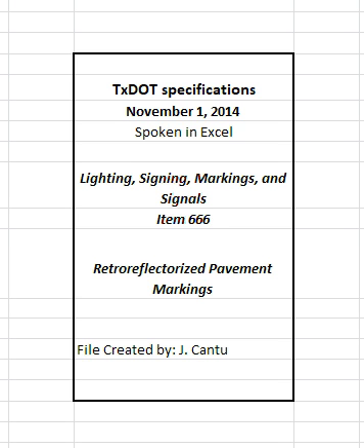Take a minimum of 10 more measurements after 10 days of this second application within that mile segment for that series of markings. Restripe again at the contractor's expense with a minimum of 0.060 inches, 60 mils, of Type 1 marking material if the average of these measurements falls below the minimum retroreflectivity requirements. If the markings do not meet minimum retroreflectivity after this third application, the engineer may require removal of all existing markings, a new application as initially specified, and a repeat of the application process until minimum retroreflectivity requirements are met.